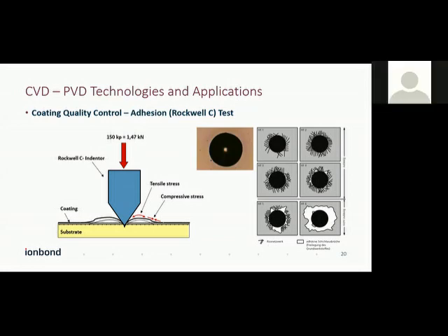So what is the temperature at which PVD is done? And is there any adverse impact on core properties of parts like hardness drop, structure change, etc.? As I have explained, the PVD temperature is from 200 centigrade to 450 degrees centigrade.